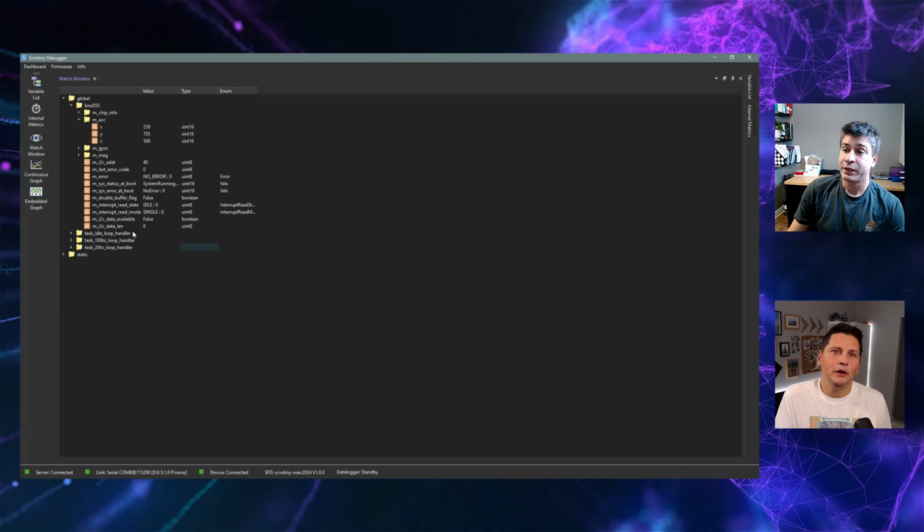Yeah. And interestingly, I was talking about printf at the beginning, and you were mapping out functionality versus complexity and so on. You could see printf all the way down there. Here we are in concept doing the same thing, right? Because you use a serial connection to send the variable value. But instead of having to go and write everything everywhere in your code, printf this value, printf this value, you don't have to instrument the code this way. You're basically instrumenting the firmware so that it will send the data you request through that server and that bidirectional connectivity. Is it described correctly? Yeah, pretty much. Okay, awesome.